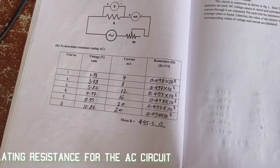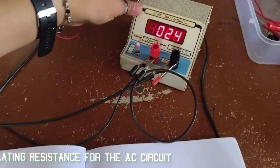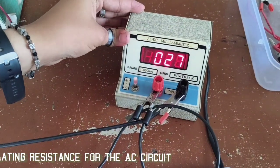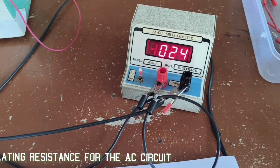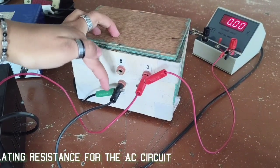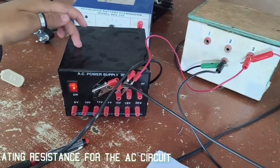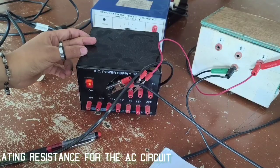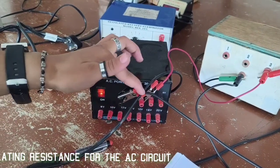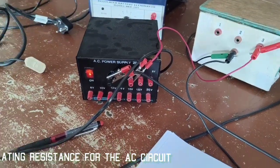Okay, so now we have to find the same thing but using an AC circuit. So we changed the ammeter to 2000 milliamps because we need a different range of current values. Now the pins will still be at 3 and 4 because it's the resistor, whereas your power supply will be an AC power supply. So one of them will be fixed and the other one you can vary by changing the pin from 2, 4, 6, 8, 10 and 12 volts.